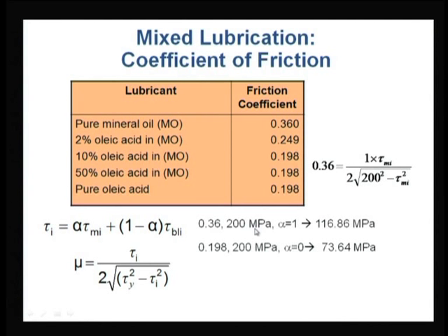Wherever there is adhesive bonding, if you use a lubricant, there will be a slippery action happening there, and cold weld junctions will not form if there is a slight relative velocity. Of course, if there is an excessive load, even in the presence of a liquid there is a possibility of cold weld. But if there is some lubricant available, even when the load applied is high, the interface shear strength will be lower than the bulk metal shear strength, which is by and large what happens whenever we do experiments in the lab. We found interface shear strength is lower than bulk shear strength.